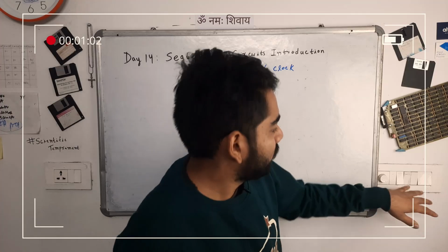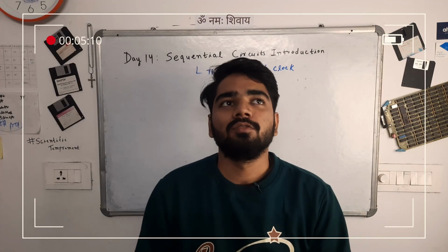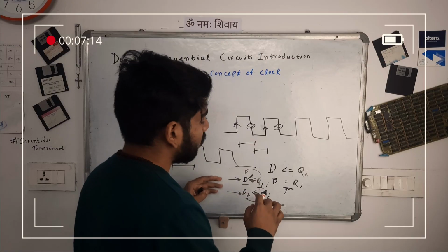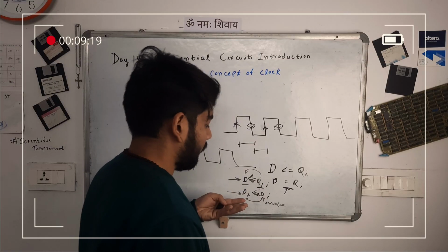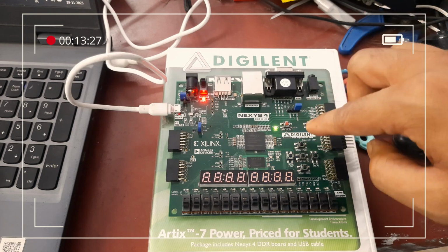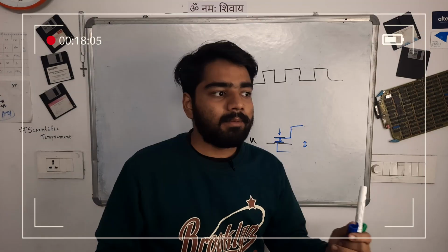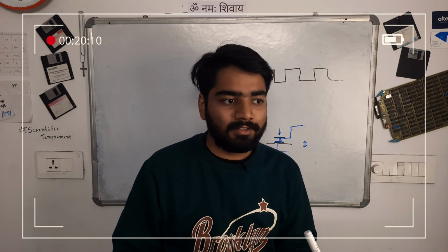the lights. Let's say if I turn the lights off, it will be off. So what is a clock signal? So this D will not get the value of Q immediately, right? We need to generate a clock. Like, it's not toggling every time. Like, if I push it, you saw it didn't toggle. There are two main reasons for this. Bouncing of the button is one of the most important ones. Many beginners get confused when these kinds of things happen.